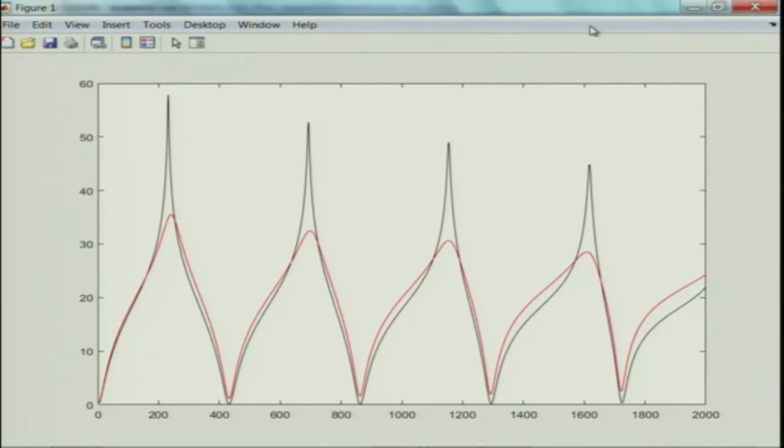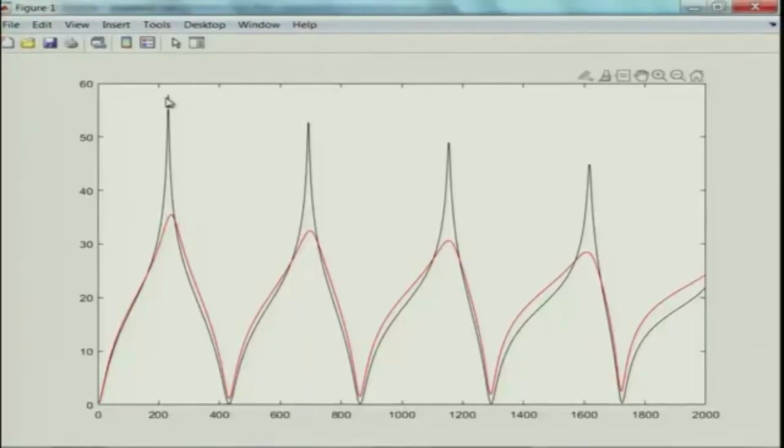So, you keep getting the same kind of conclusions again and again. But of course, these results cannot be completely relied upon, even in the low frequency range, for flow reversal configurations, because for flow reversal configurations we really have end corrections. So, even the peaks that you are seeing here will be shifted towards the right side of the spectrum because of the reduced effective length of the chamber. So, these are all end correction matters.